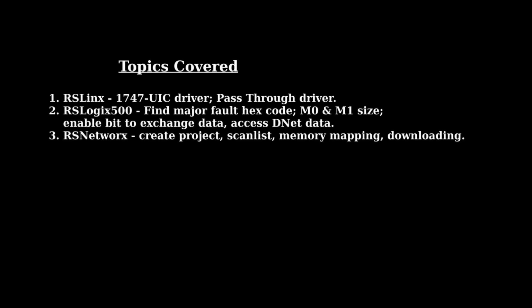We're also going to use RSNetWorx to create a project via drag and drop. We're also going to configure the scan list, do memory mapping, and download everything to the DeviceNet scanner. Now, if you understand all of the tools that this video covers, you should be very well on your way to maintaining these networks, making small modifications, and generally being able to do whatever you need to do with an SLC DeviceNet system. Without further ado, let's get our hands dirty.